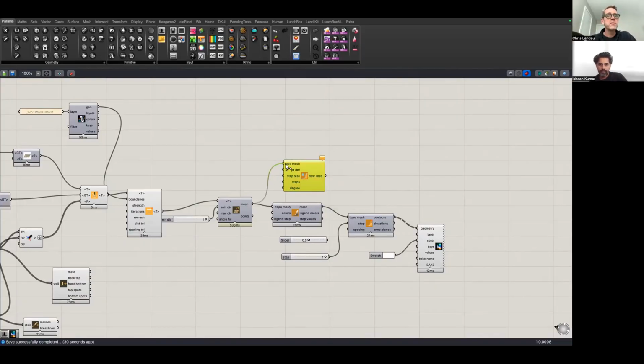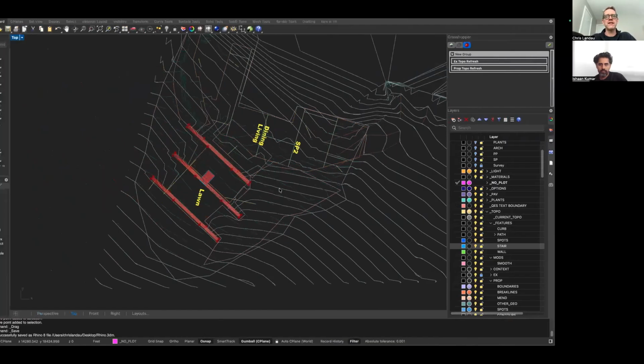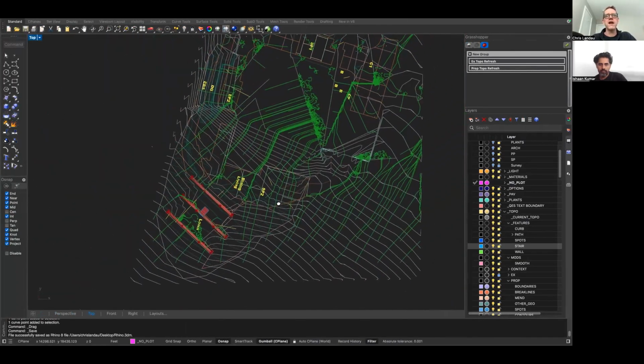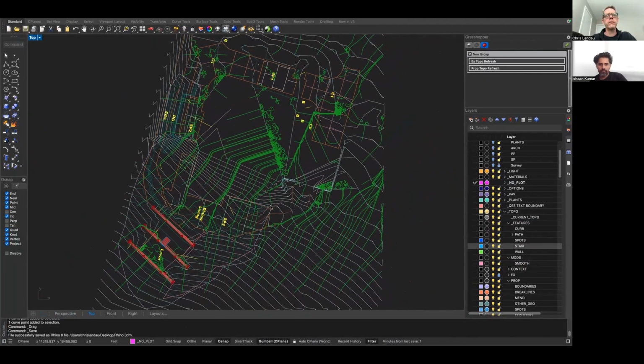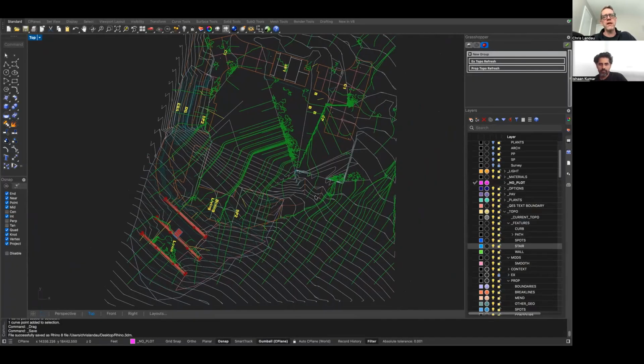So we just plug that in for reasonably sized sites, and now we have water flowing across the site. Obviously we don't have our building, but we can see where water's going. We could begin to create swales that divert that water, or know where to put the drains, right? Where to put the trench drain or whatever. And it just tells us right away. This is every 15 feet. It gives us a pretty good sampling, right? Because it's not just every 15 feet, it's also traversing all of the space in between. And we get a very good sense of where things are going.